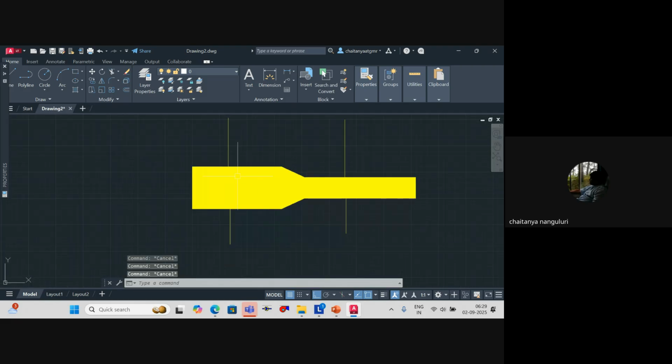Then what will happen? At this location, at the bigger size, your velocity will be higher. As the air travels further, you will reduce the velocities. The reason we do it is that for lesser air volume, if you keep the same velocity, your friction factor will increase because you will reduce your duct size also, right? So for that reason, you will use something called the velocity reduction method, where from the start to the end, slowly you will reduce the velocity. Understood or not? And the maximum velocity we try to maintain is around 1500 fpm, feet per minute.